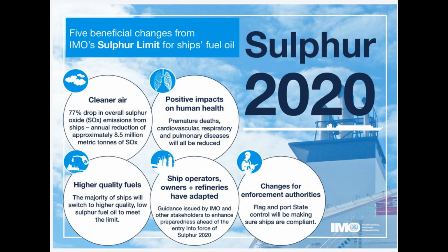For that, ships need to change to 0.5 weight% sulfur fuel from 3.5 weight% fuel, or use an exhaust gas cleaning system, that is EGCS. Use of low sulfur fuel oil is expensive but the most commonly used method to comply with Annex 6 of MARPOL.